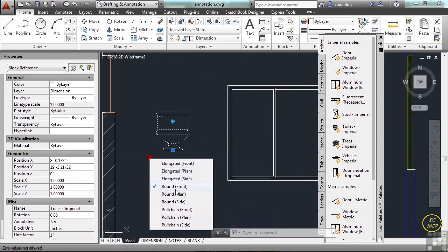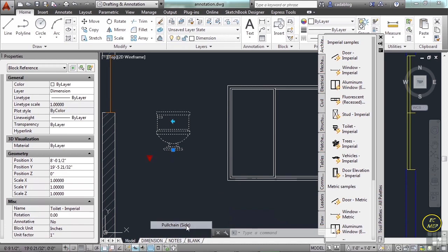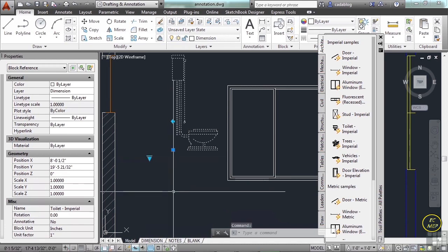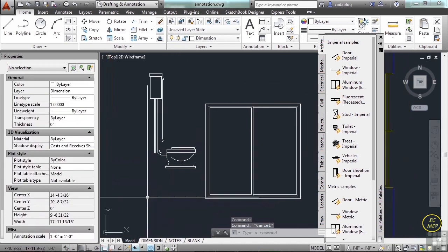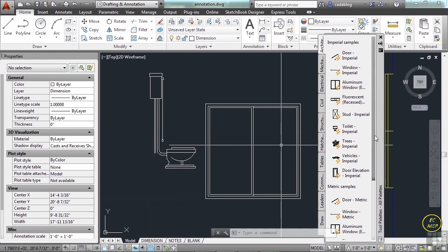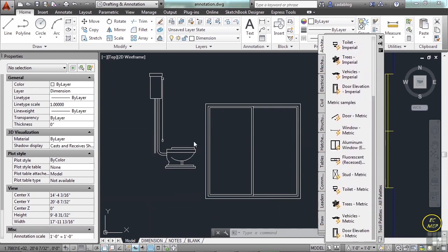And now I can have 3 different designs for these toilets, all of which are shown in 3 different drawing views. So dynamic blocks will give you flexibility. They're dynamic. They can do a lot of different things, and AutoCAD has several of them. And in fact, if you need more, you can look for dynamic blocks on the internet somewhere. Save them, use them all over the place.